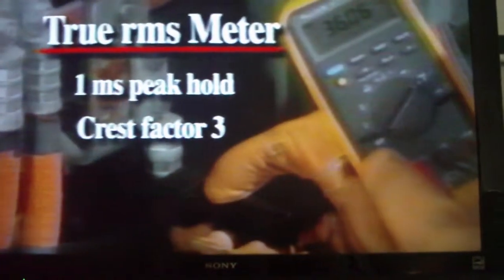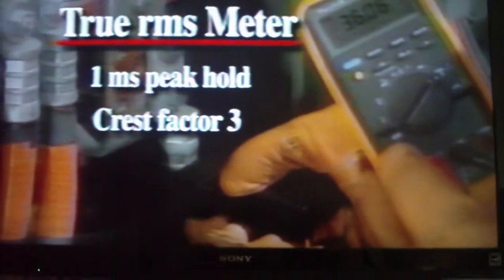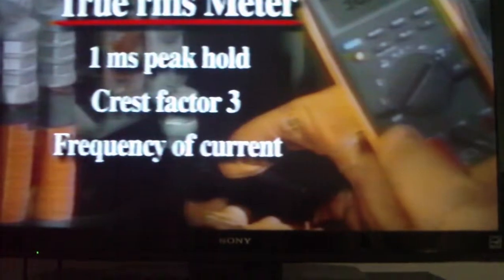Harmonics are easier to detect if you have the right tools. This includes a true RMS meter that can capture an instantaneous peak reading in 1 millisecond to capture the half-cycle peak of the current waveform. The meter should be specified to a crest factor capability of at least 3, and it should have the ability to measure the frequency of the current.